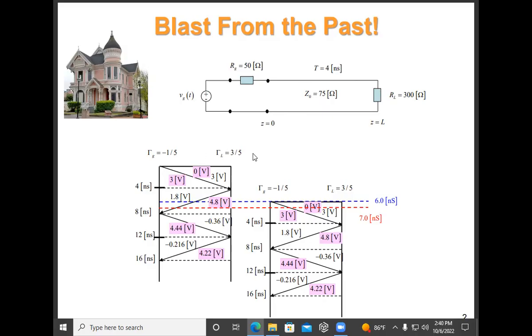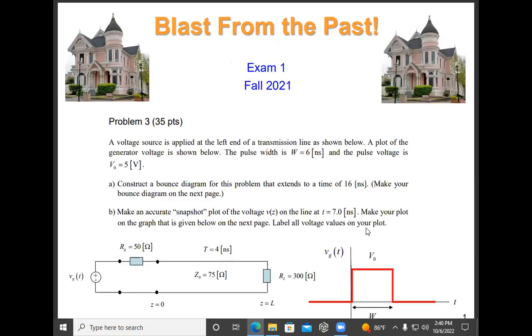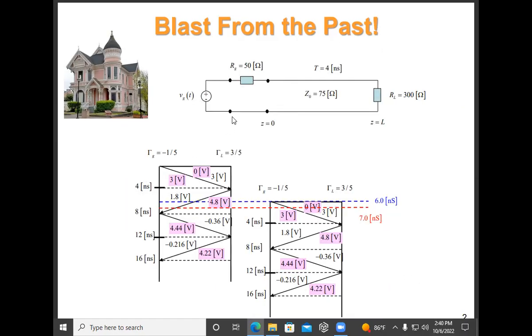Okay. All right, so first let's make the usual bounce diagram. And so again, we have the times labeled, as shown here. Now the incident wave comes from the voltage divider. Now remember, for the step function, pretend we're doing a step function right now, that's the original bounce diagram, the generator was putting out V0, which is 5 volts. But then the voltage divider cuts down that 5 volts. What's that A term going to be, as we call it in the notes?